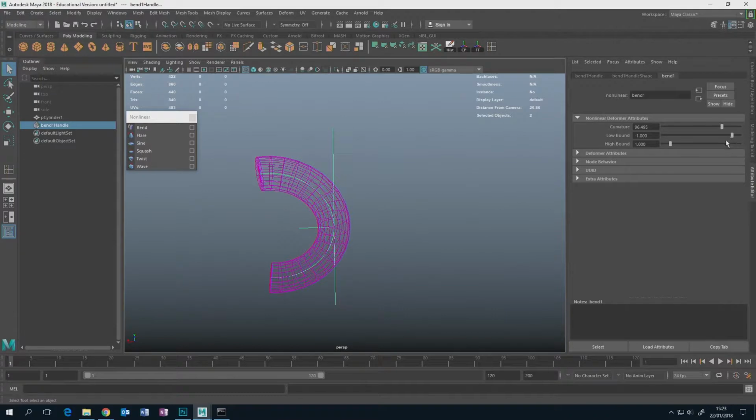And absolutely any of these menu commands, if you hold down Control and Shift, it will create a button just here. But what settings? Some of these have got like settings on them, haven't they? Well, when you hold Control and Shift, it'll put that command onto the shelf with whatever settings you have set in here last. That might catch you out. So just be aware of that.